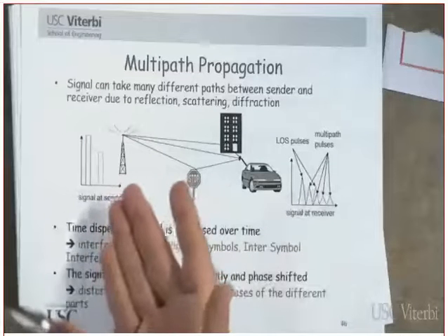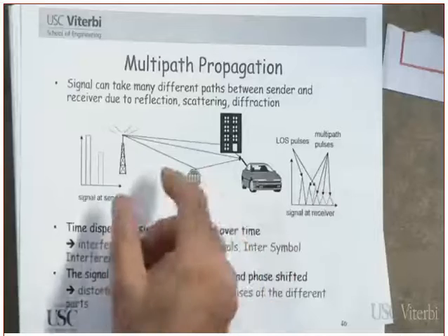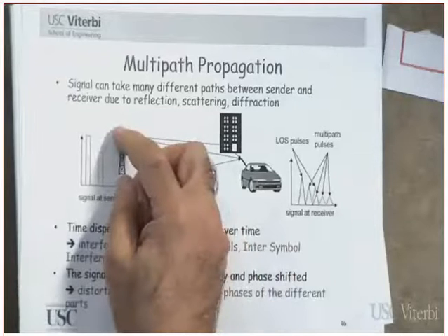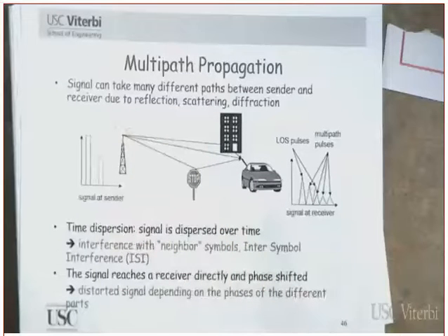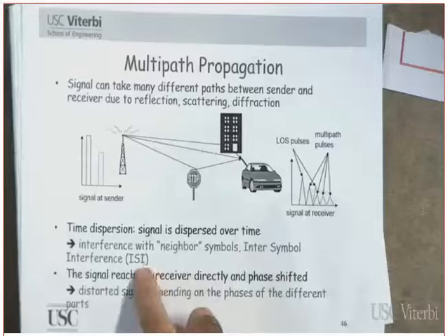It is the same transmission. You understand what I'm saying? In other words, it's coming from the same base station. One symbol will interfere with another symbol because of the difference in the delay. Clear? Generating what is known as ISI.